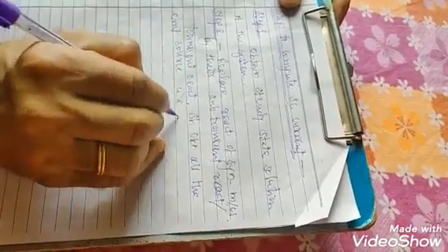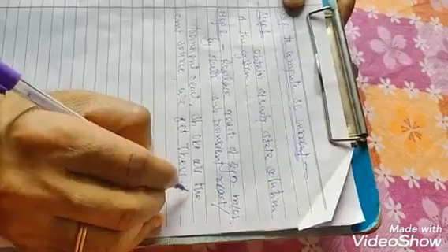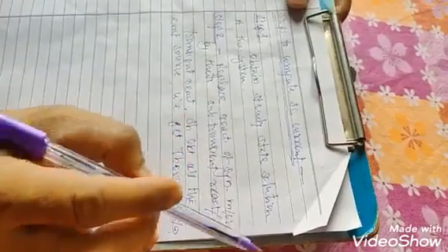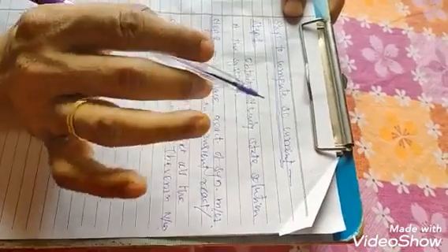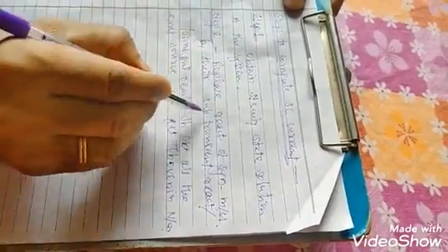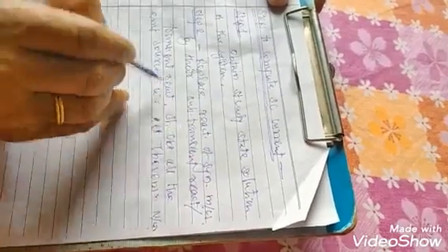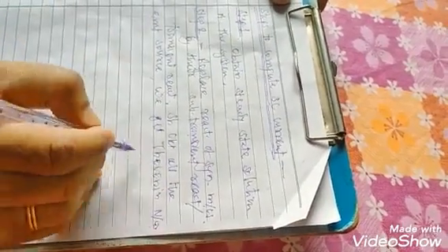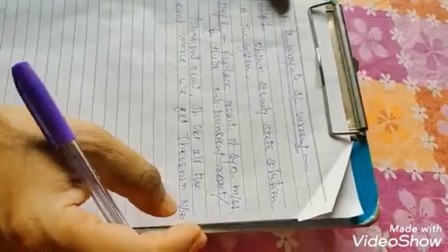So we get the Thevenin network. So the first step is to obtain the steady state solution for the given system, which is the load flow study. Step 2 is to replace all the steady state reactances by their subtransient or transient reactances as per requirement, and short all the EMF sources. So we get the Thevenin equivalent network.